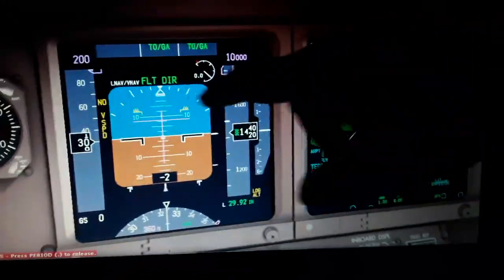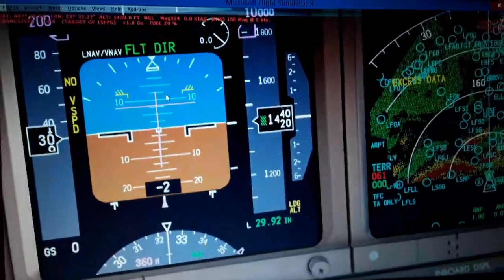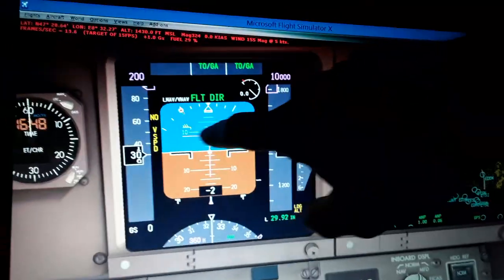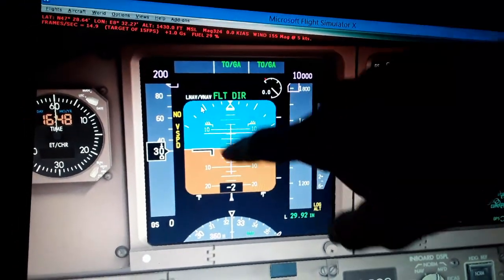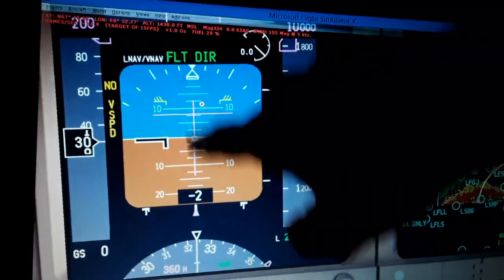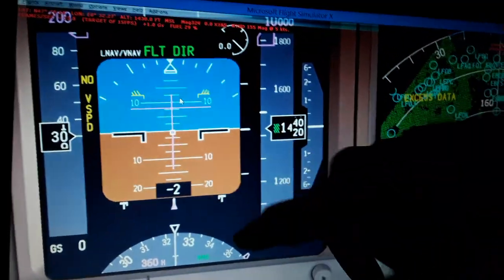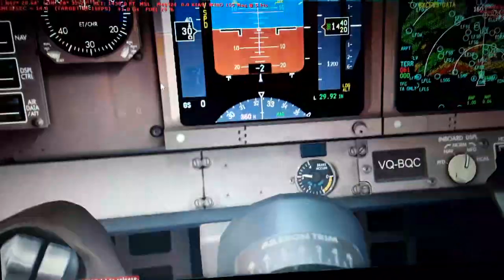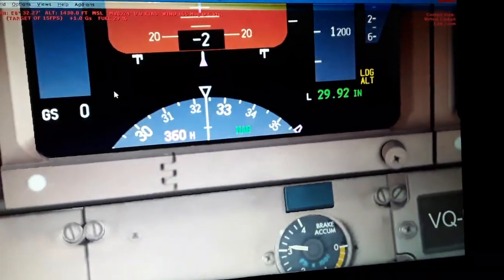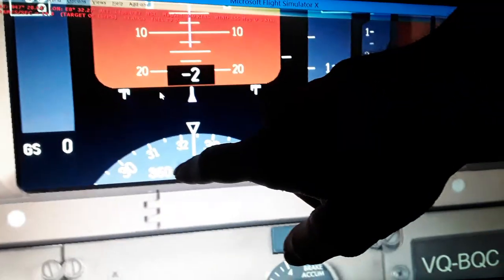So you have here also the barometric altitude above the sea level. Right now it's 1430 feet. The rate of climb and descent tape 10,100 feet. We have the altitude indicator with the flight director crossbars and the autopilot crossbars, and the pitch ladder indicates bank angle limit, and the localizer, the radio altitude above the ground level 2 feet, and we have the magnetic heading here is 300, approximately 324.